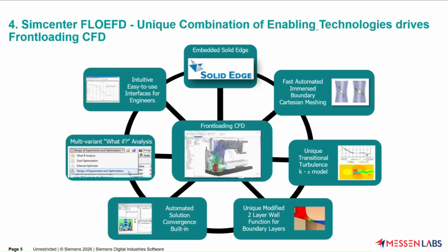So for today's demonstration, I will be using NX, which is the CAD tool from the Simcenter portfolio, and then I will be performing the simulation with NX with FloEFD. NX is integrated with FloEFD in the background. So if you want to carry out any CFD simulations, first thing is you will have to have a native CAD software on which you are designing. On top of that, if you are integrating FloEFD with that, you can perform these simulations and get your results in very quick time.